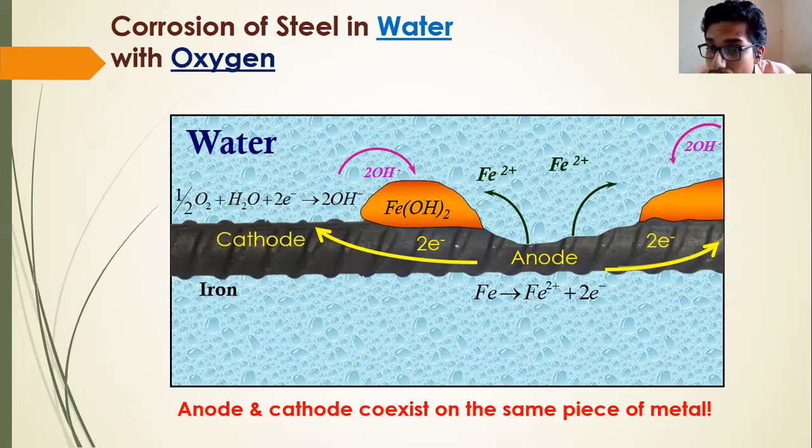Corrosion is a process where you can get both a reduction of volume and an increment of volume. Some people will say that when corrosion happens, the volume increases, and some people will say that the volume decreases. If you see it from the material properties of the metal, you can say that the volume decreases because the material is going to deteriorate due to the corrosion process. But if you see it in the whole system of concrete, we can say that due to the corrosion, the volume expands or increases.